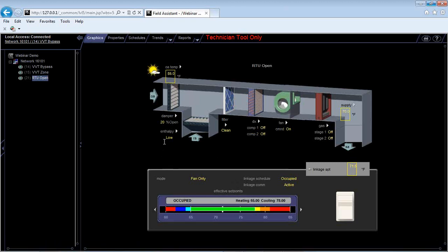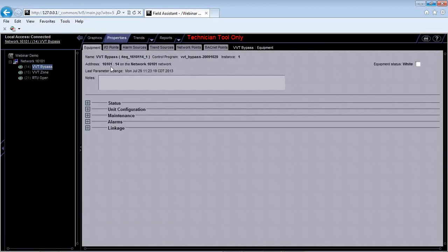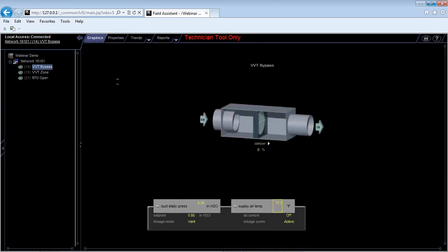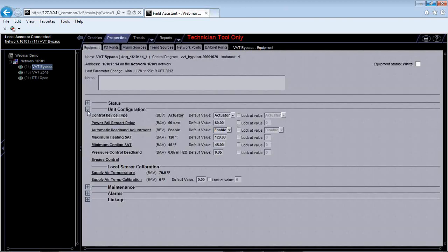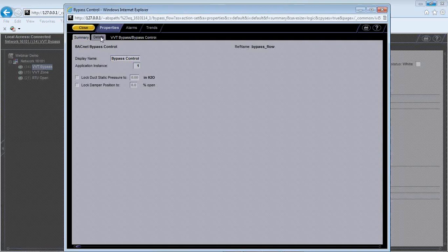There's not much more to do other than configuring the bypass. The bypass, what you want to do is you can set up your set point for the bypass controller of how much duct static you want to set. So, I'm sorry, you can do it on the graphics page. If I just click on duct pressure here, oh, wait, no, I'm wrong. If I have to click on bypass control here, I'm sorry. I should have known that.